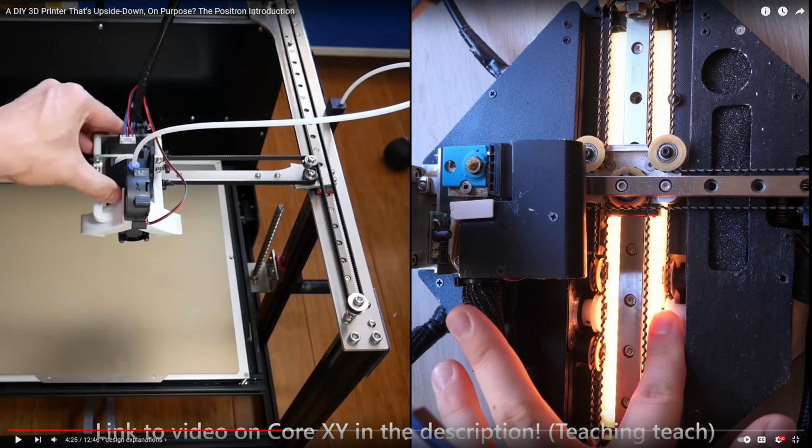So he uses these, he'll talk about it. Basically, these are like timing belts that have this kind of grip thread on it, but you have to worry about the belt twisting when it's making these turns. That's why he's not using belts, because the belts will twist, and when they twist, you could have issues of them coming out, and the tolerancing being difficult to keep because of that turning. So in this case, there's no twisting because it's just a straight cable, and yet it has enough grip so that you don't have to worry about slipping.